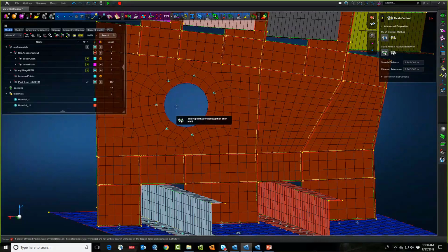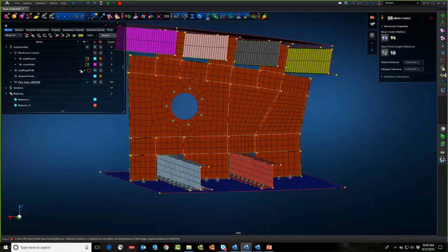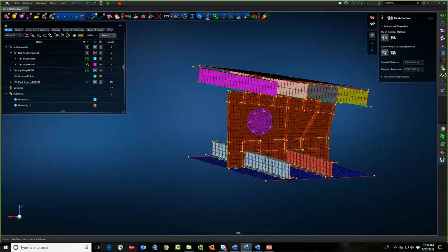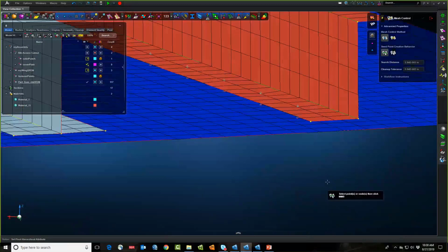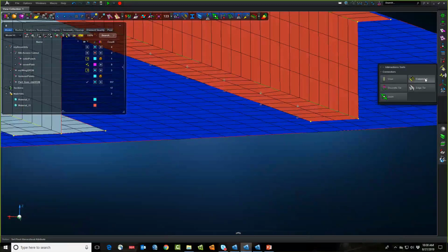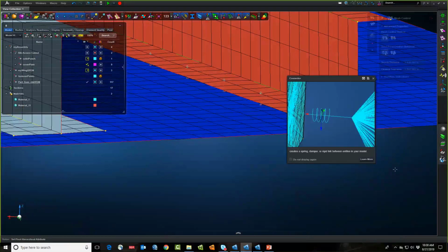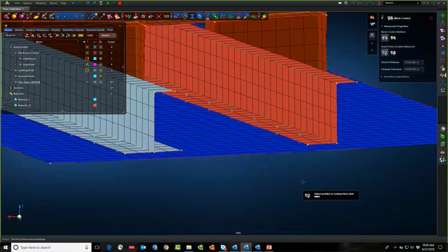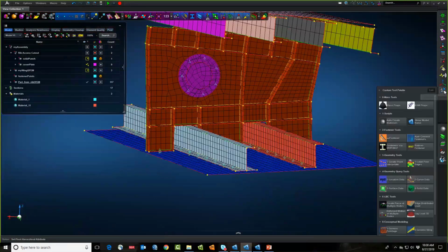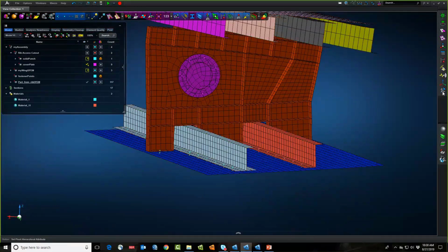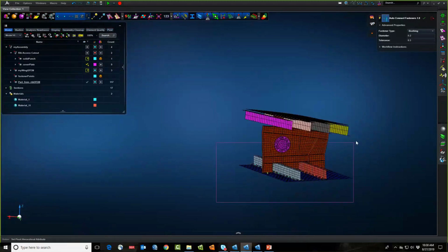These are called seed points in Apex. I've also got a cover plate here for my access panel. And the next thing that I would need to do is to actually connect the points to create the fasteners. It's really easy to do. We have a nice connector tool in Apex that does that. Allows you to click, click, click, click. But in this case, I've got a lot of fasteners. I really don't want to click, click, click, click. So I will use a script, and this script will allow me to actually create them all at one time.